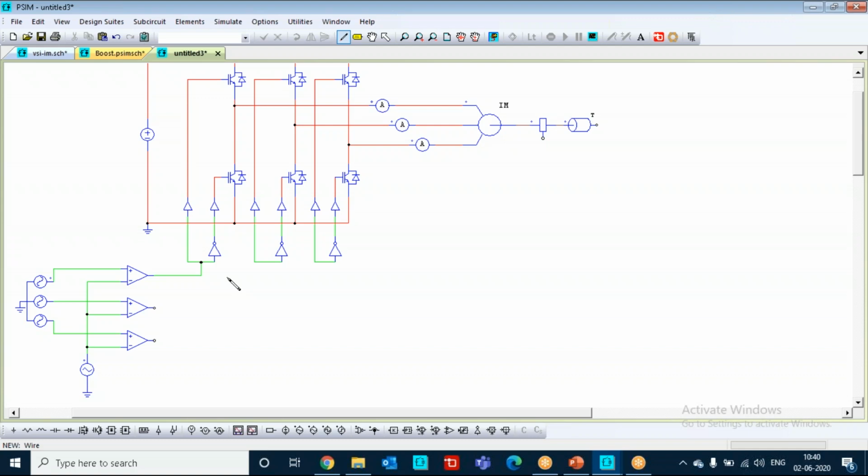When you are using phase regulators, meaning voltage regulators, you have to give the duty ratio. Here we are doing inverter operation, which doesn't require that. You need to give a reference sine signal, so maybe it is sine PWM or space vector PWM.